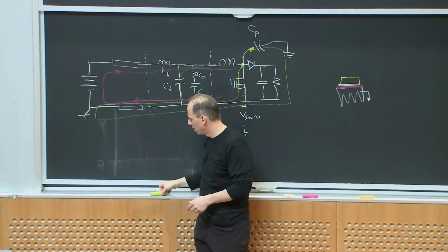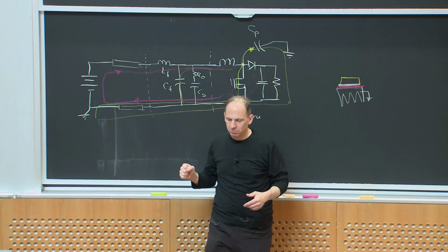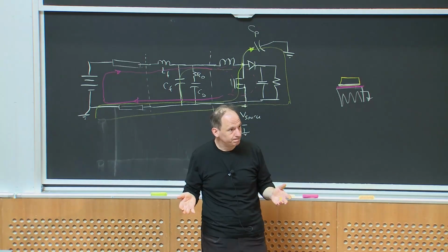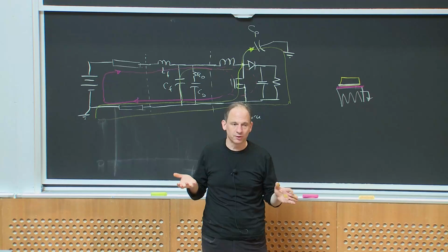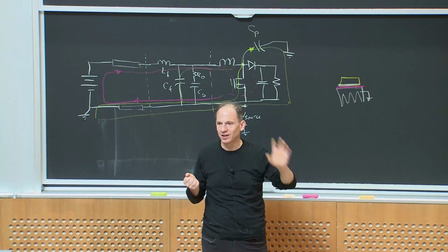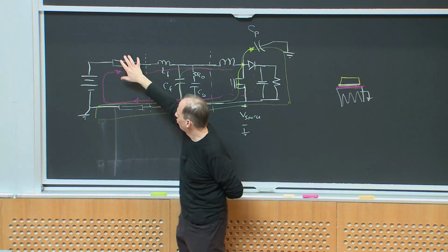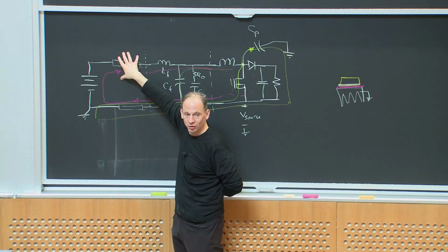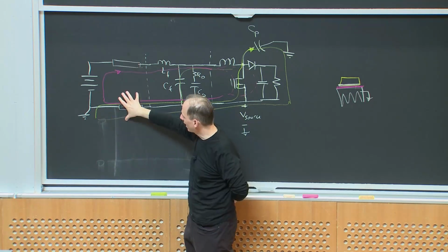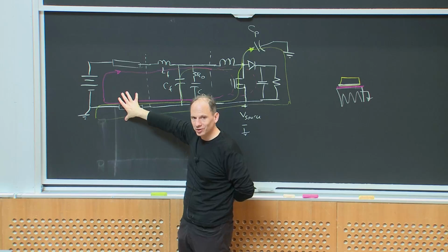And this is a problem. I mentioned earlier in the class, when we set up our line impedance stabilization network to measure everything, usually you have one LISN for measuring the noise on the hot line and another LISN for measuring the noise on the return line.